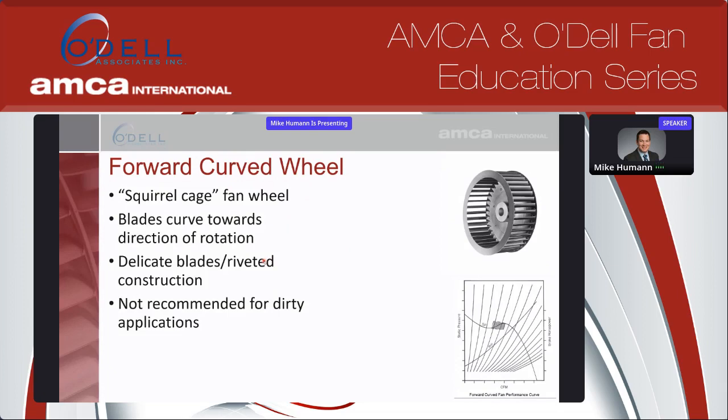As you can see, a lot of the blades are riveted. You do see welded construction on larger ones, but they are delicate, can't handle material. So that's kind of the offset there: for the price point and the application, they're much lighter duty. You kind of see here some characteristics of the forward curve fan curve. You can see here you have this region of instability just left of the peak static capability of the fan. So you're going to want to be operating this in this section.